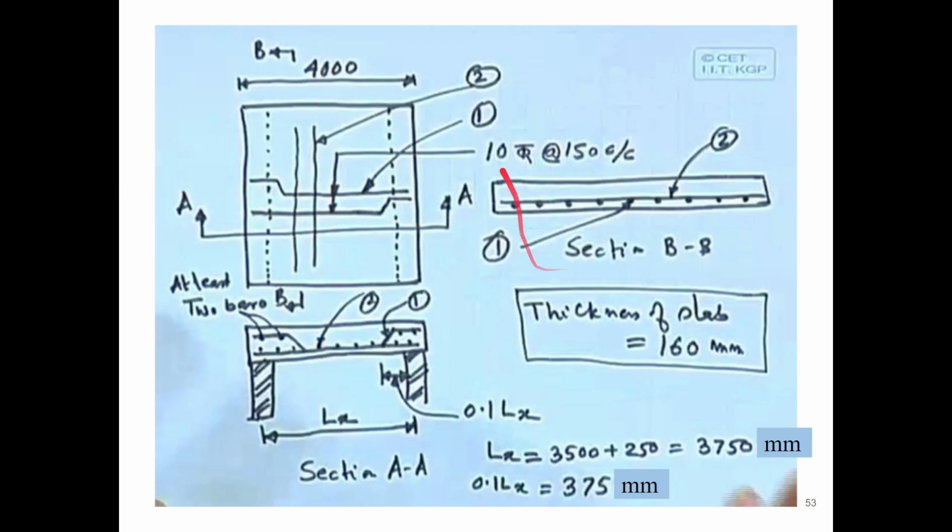You can see here also, if you cut the section AA, these bars are this line. They have also provided bent up bars, and two is the dotted bars. This is the opposite to the beam condition. In a beam, these would be the reinforcement bars and we don't provide the secondary one. Instead we provide the stirrups. Here the stirrup is not required; that much is not mandatory. If the condition is satisfied, we don't go for stirrups because it will be unnecessary and costly.